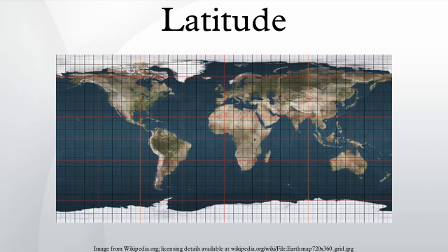Map projections from the sphere. On map projections there is no simple rule as to how meridians and parallels should appear. For example, on the spherical Mercator projection the parallels are horizontal and the meridians are vertical, whereas on the transverse Mercator projection there is no correlation of parallels and meridians with horizontal and vertical, both are complicated curves. The red lines are the named latitudes of the previous section.